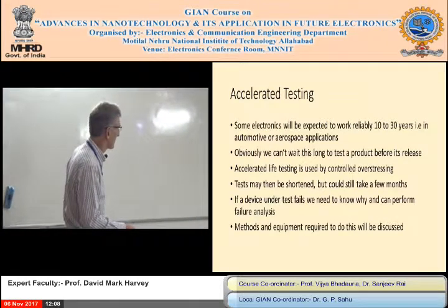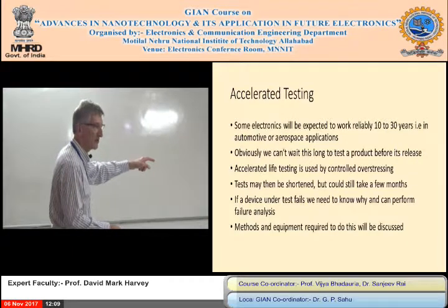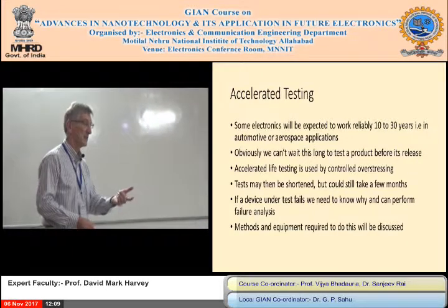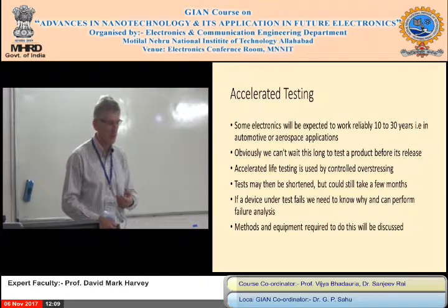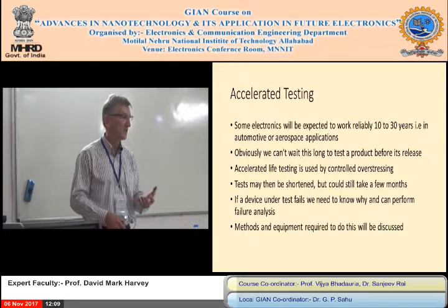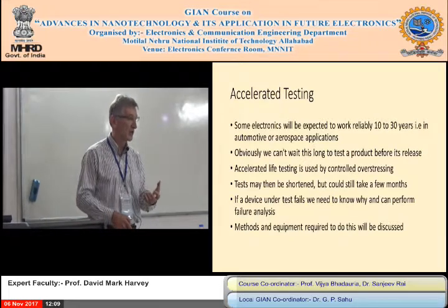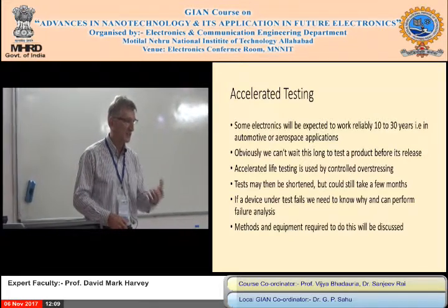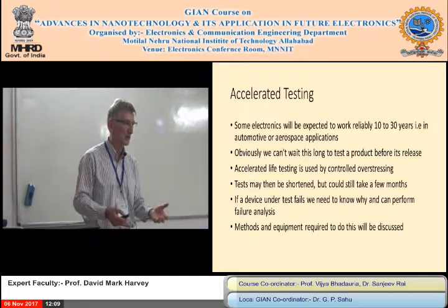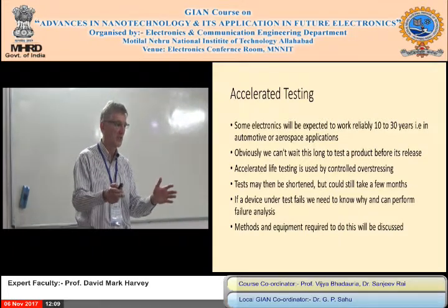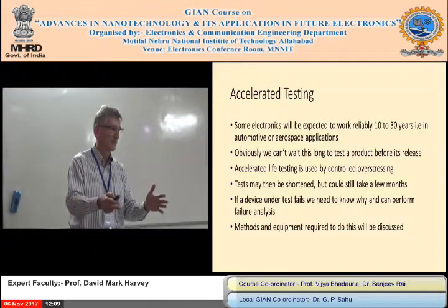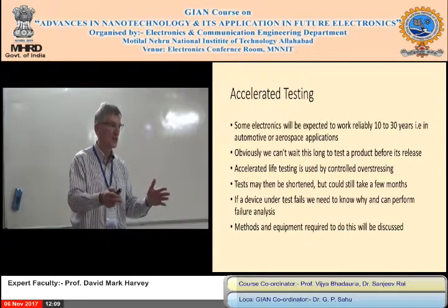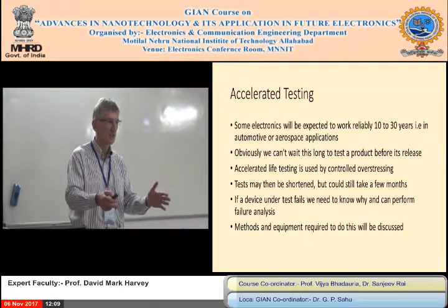It's sufficient, but it still takes a few months to do the test. And we can't be 100% sure. If you're a car manufacturer, you're confident, you've got the expertise. There's a lot of empirical formula in this. So again, it's not textbook engineering, you learn from your experience. If you do a certain vibration test on an engine management system for a car for say 2 months, and it passes, you know 99.99% it's going to last 10 years.